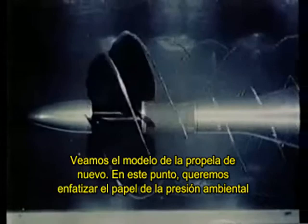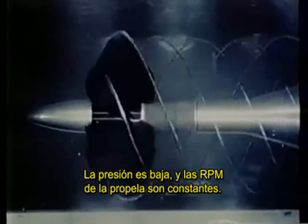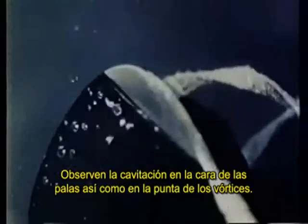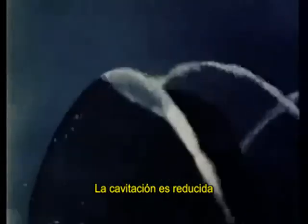Let's look at the propeller model again. At this point, we want to emphasize the role of the ambient pressure. The pressure is low and the propeller RPM is constant. Notice the cavitation on the blade faces as well as in the tip vortices. The pressure is now being increased by raising the pressure of the gas above the water surface. The cavitation is reduced, and now it is almost suppressed.